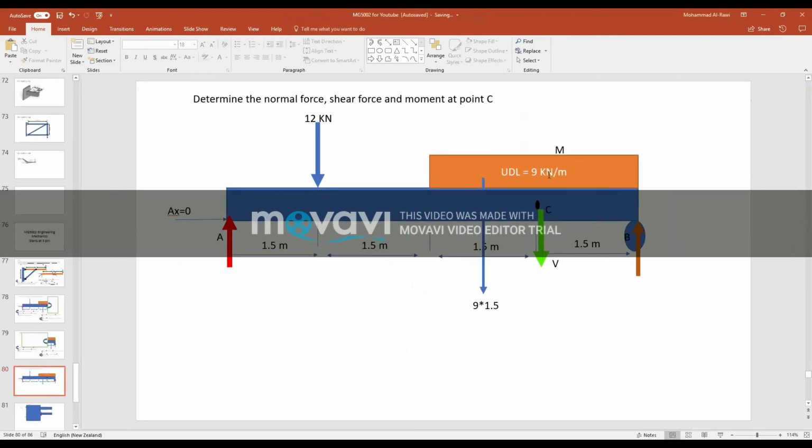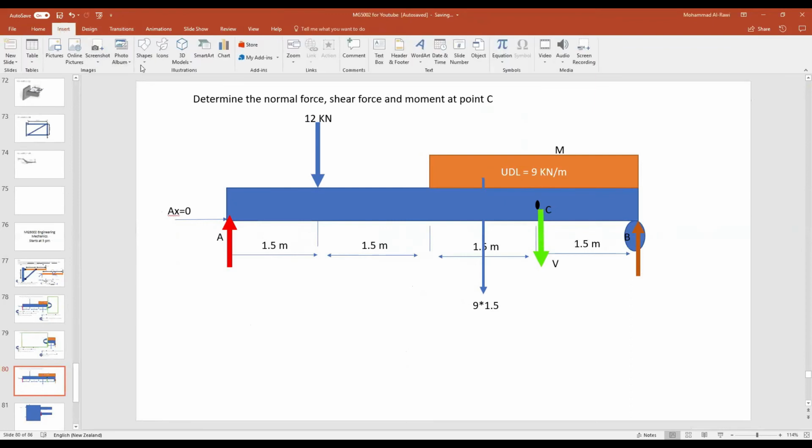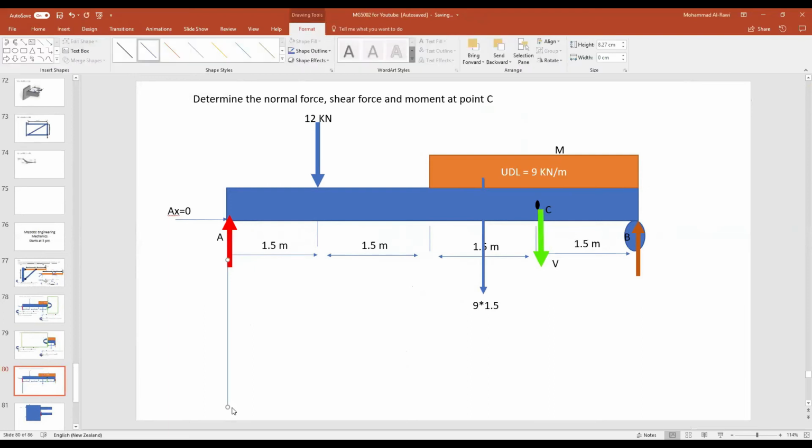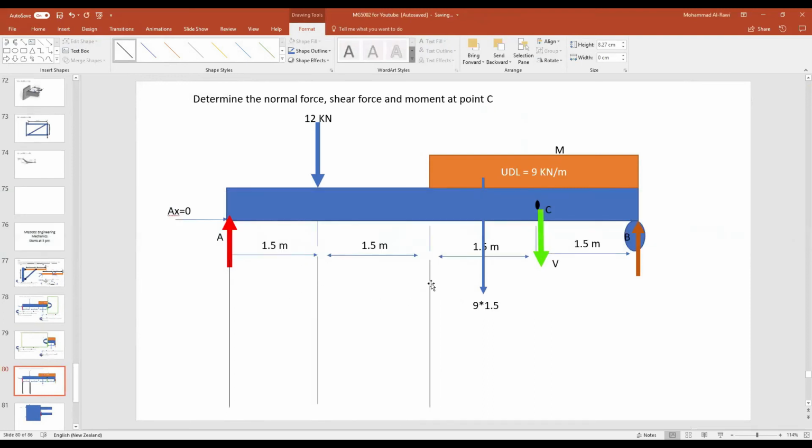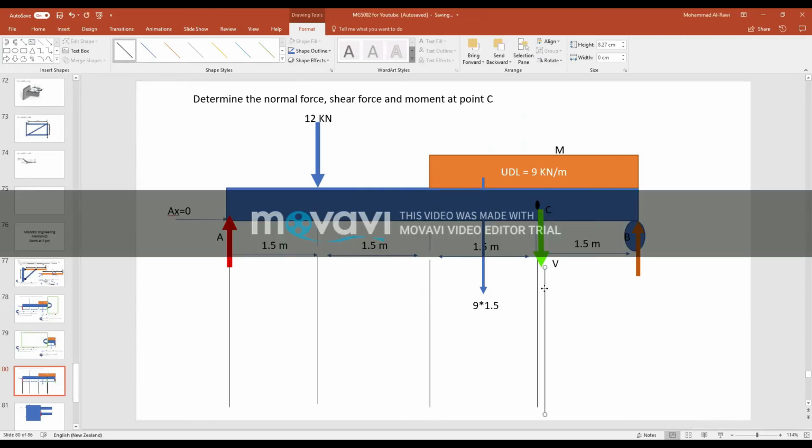So technically, what I recommend all the time, guys, and please remember this in your tests, is always project the lines wherever you think there is a possibility of force, and use this as a reference point. You can make it a disconnected line or a connected line. Please remember to bring calculators and a ruler, or something to make your drawing tidy and clear so you don't confuse yourself. Hopefully this will help us find a very nice shear force diagram.